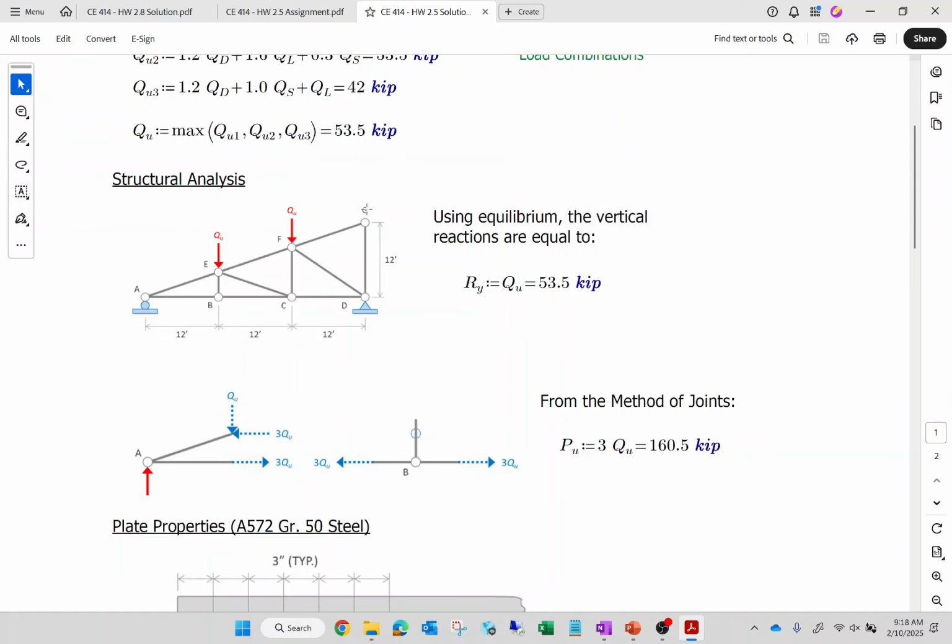For this one right here, if I have Q up, I have to have Q down. And so this is what? Over 12, up 4. So if this is Q, that's got to be 3Q. And so if this is 3Q, that's 3Q. So that tells me the interior load based on this joint is 3Q. Is that okay?